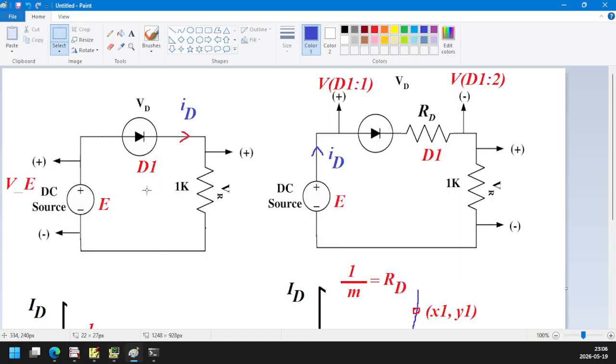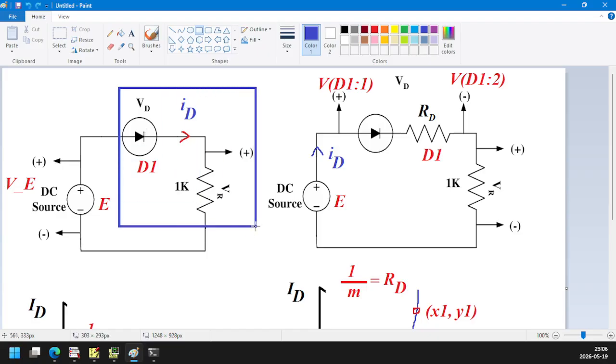So we are basically simulating this circuit. This circuit is taking the voltage across the voltage source and the current. That means we are actually taking the diode and the resistor together. Because if we consider these two as series elements and one single element, these two elements are in parallel with this one. So the voltage across the voltage source is actually the voltage across the diode and the resistor combined.